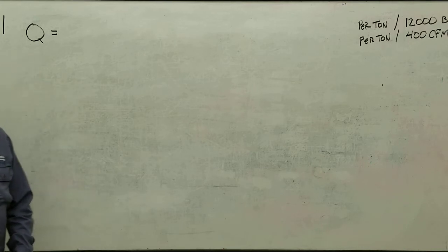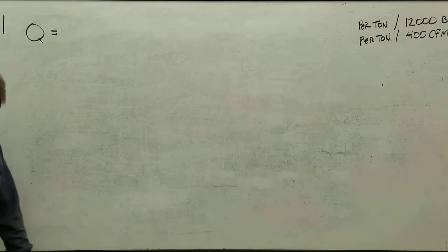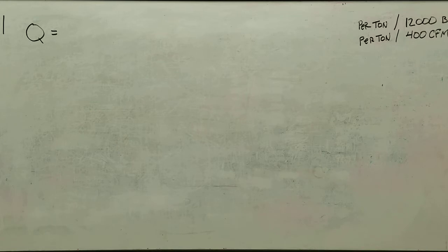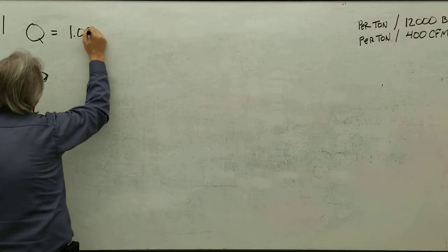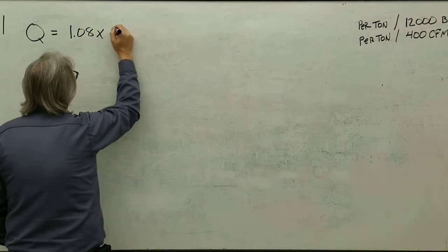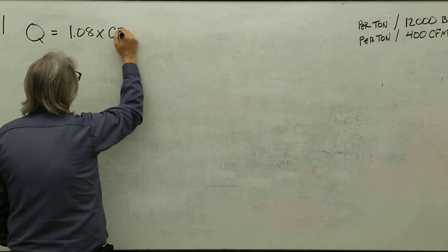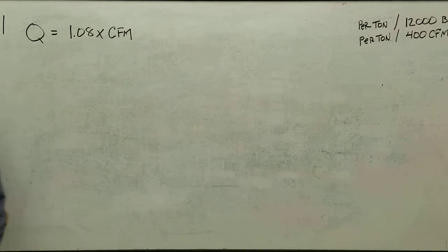Total heat. Q is equal to 1.08 times CFM times the temperature difference.